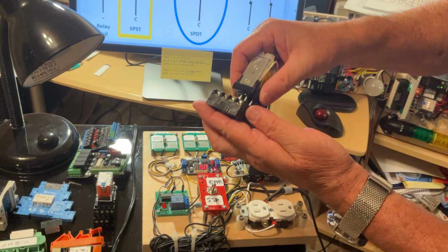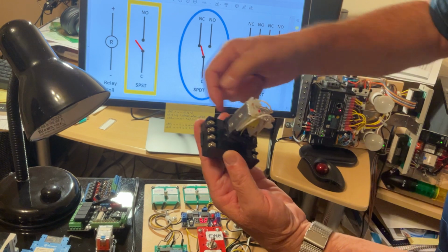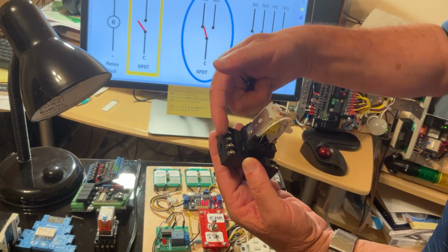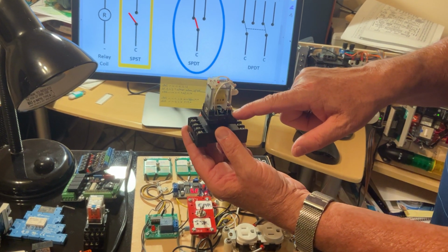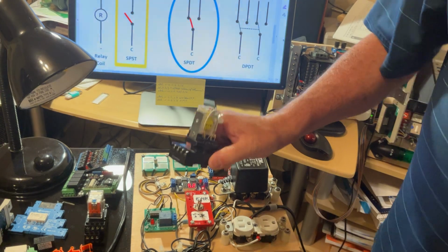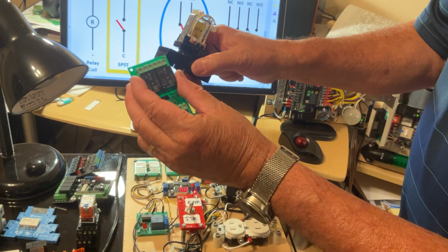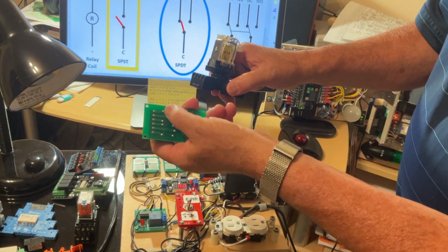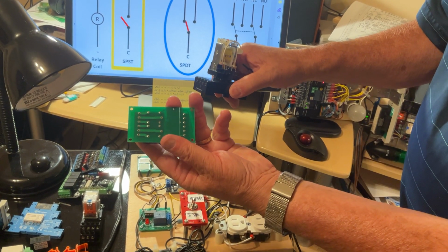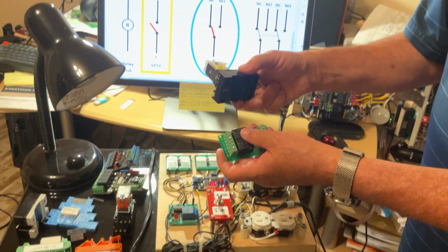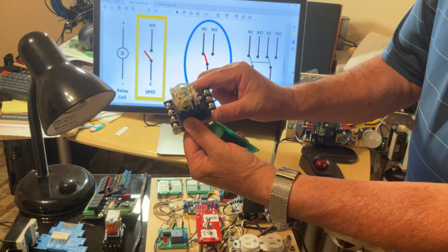So when you really have to deal with the wiring of the relay, you're going to connect thick wiring out of it. Why thick wiring? Because most of the relays like this one, they can draw over 10 amps. So for big amperage, you need big wiring. And if I can show you what is the equivalent for a printed board relay, take a look how thick the wiring has to be in order to sustain the maximum amperage the manufacturer gives you in the specs. Okay? So this is about the connections for a standard electromagnetic relay.